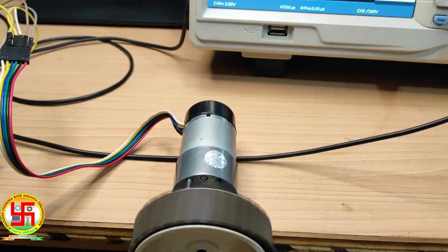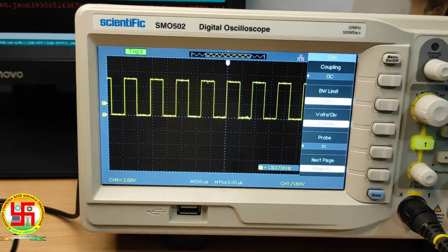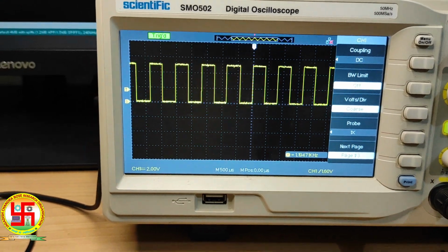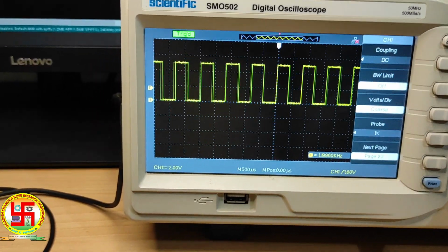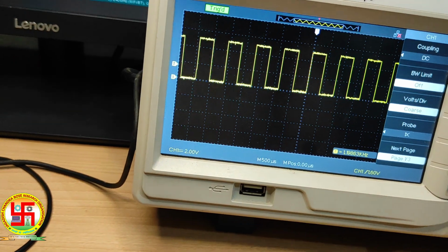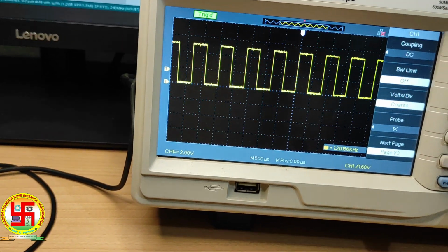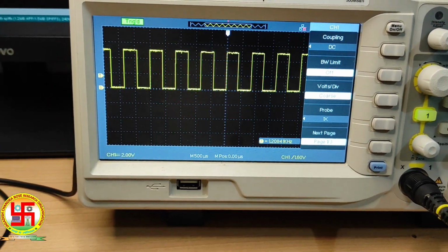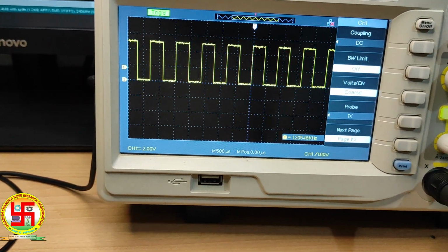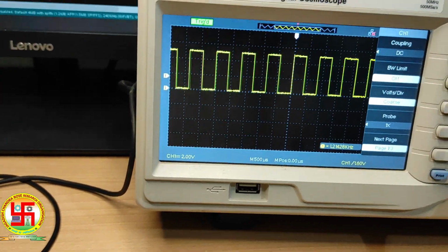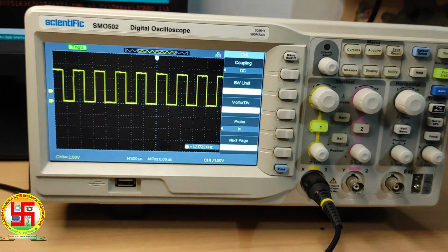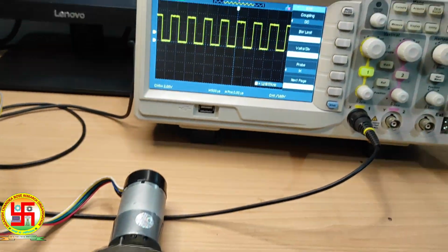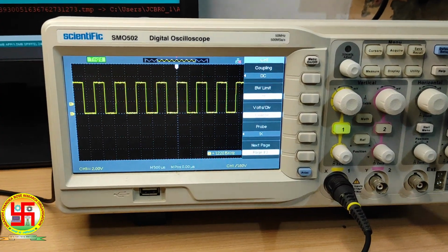It is running at a particular speed, and if we count the number of pulses coming in 1 second, from that information we can compute the RPM of this DC motor. After counting the number of pulses we can also measure how much distance this motor has covered in centimeters or meters. So this is all about the working of encoders, and this was the example of an incremental encoder.